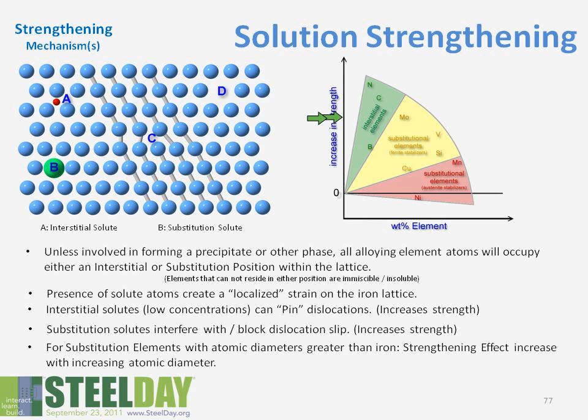And again, this is a very rough cartoonish type graph just to give you a feeling of how these things interact. If you take all these various elements and their influences on strength or weldability and consider them just to be carbon and what that effect would be, that is your carbon equivalent. It's basically a mathematical modeling to predict.